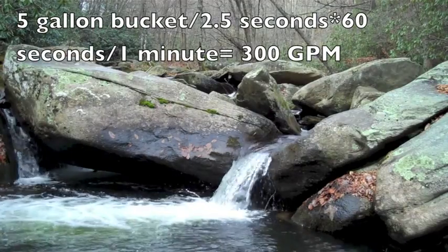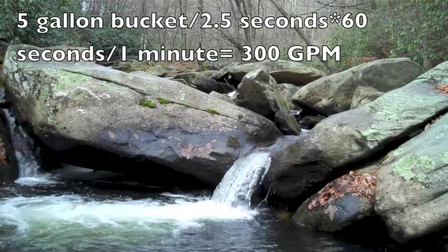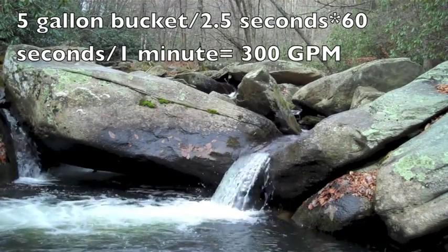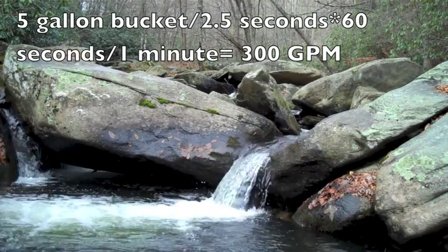So here is a hypothetical site where you could catch all of the water. If you filled a 5-gallon bucket in 2.5 seconds, then this stream would warrant a 300-gallon per minute flow.